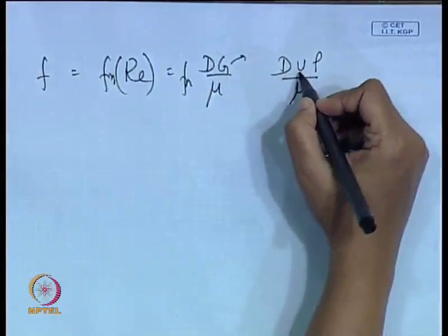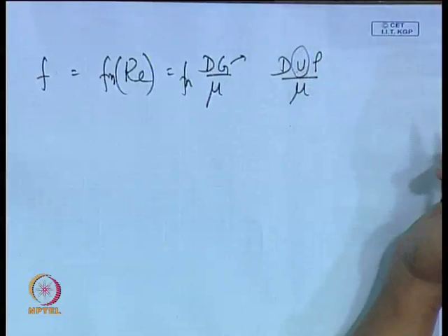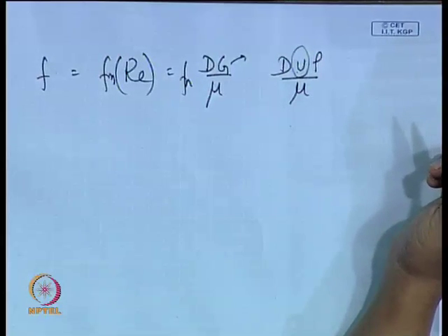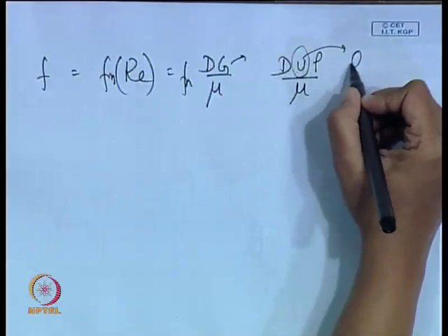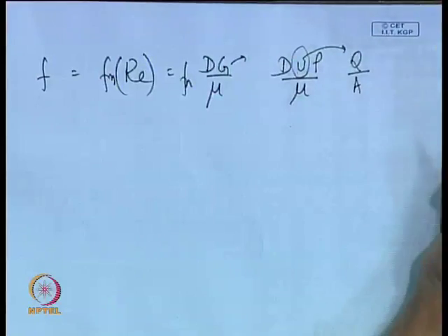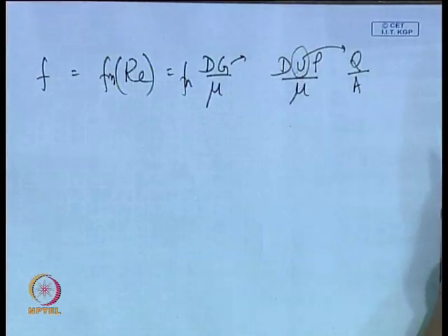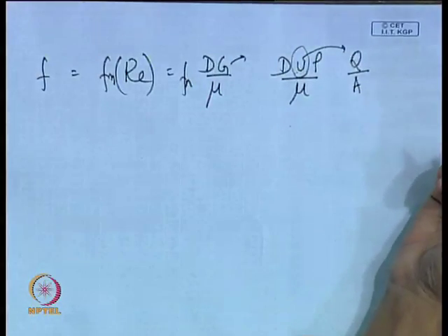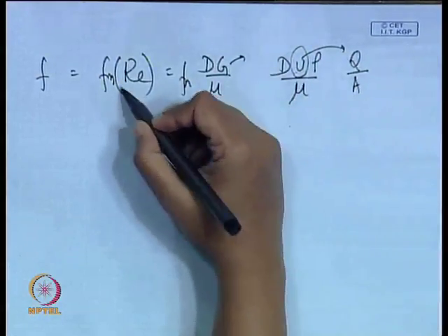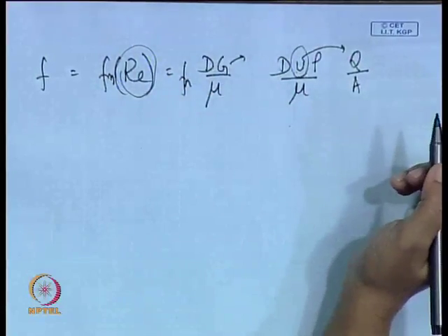There was no chance of u varying within the flow, there was nothing like in situ and input velocities. This u was simply the volumetric flow rate divided by the cross sectional area. D is the pipe diameter, and rho and mu are simply fluid properties. So this Reynolds number was an input there.